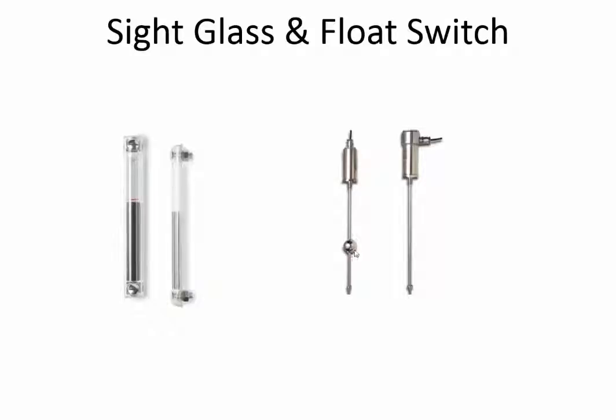Or we can have float switches, which give a level indication. We call this a type of transducer. It's giving an electrical signal according to the level on that float. These are more often used as alarm points. So when it hits a certain point, then we trigger an alarm for a high or a low level alarm, but they can be used to also indicate level as well.